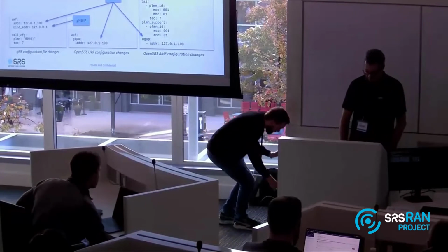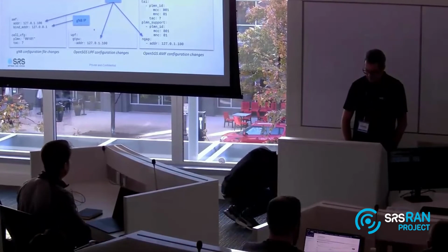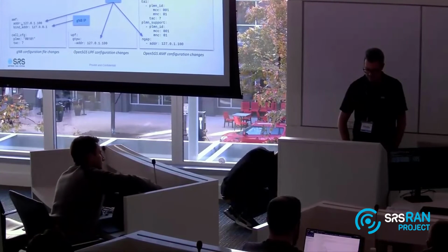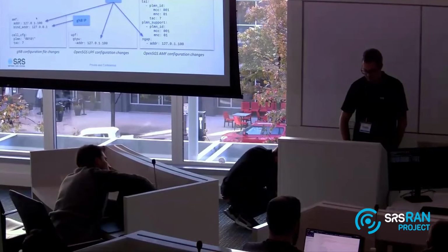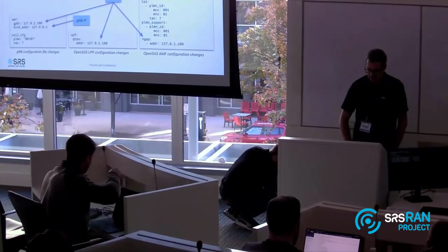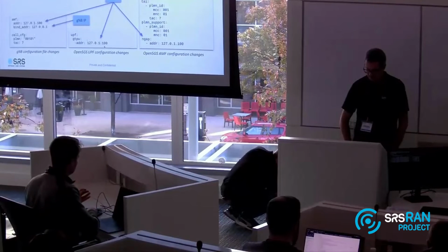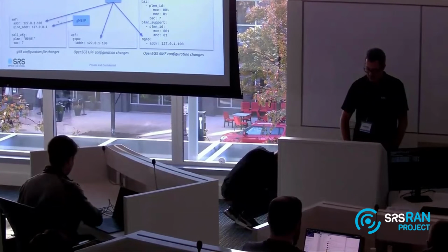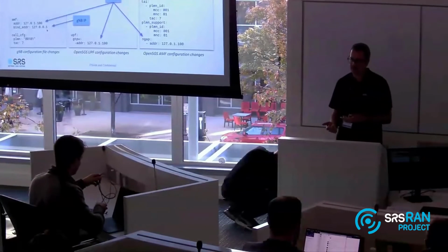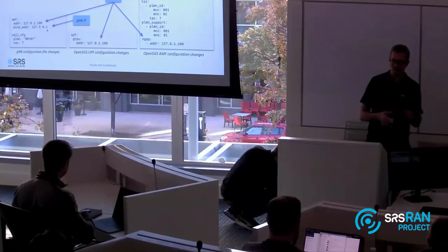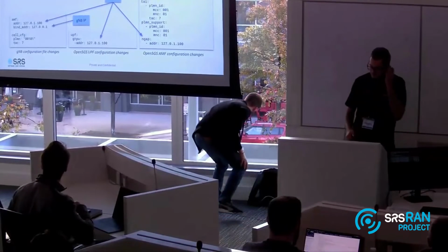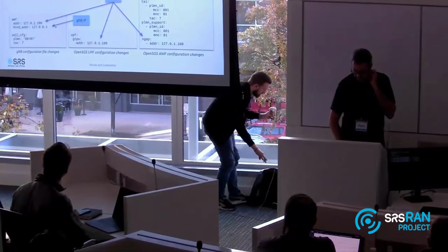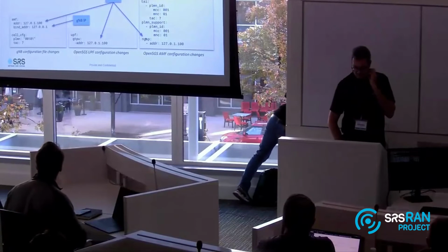So then you need to make sure that, to connect the gNB with the core, in this case Open5GS, the AMF address here matches, and the UPF and NG IP addresses, and the bind address, which is the address that the gNB will create to receive packets from the core. This one you don't need to specify in the core.